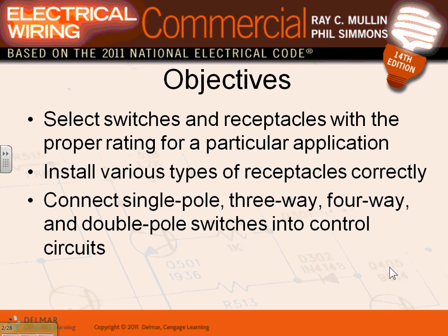Single pole, 3-way and 4-way switches, guys, they're not used a whole lot in a commercial building because of the energy code. You need to have more automatic control of your lighting system than in a dwelling. So you're going to see a lot of the stuff for the switches that we have in our building right now. They're asking about low voltage switches.